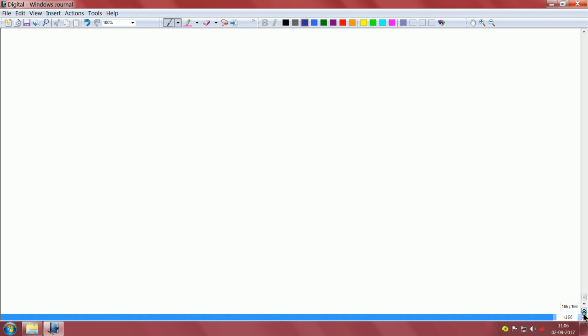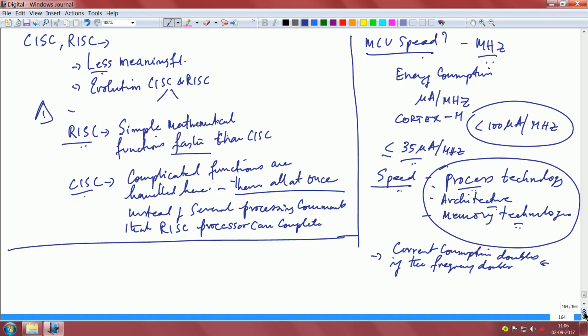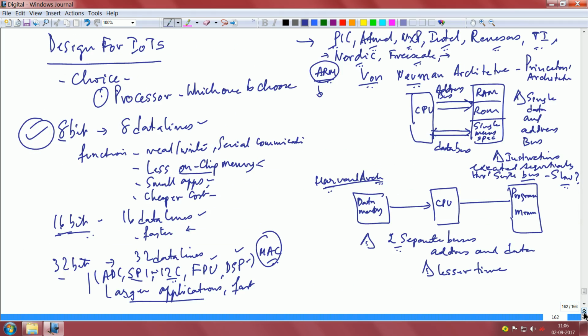Look at the architecture: the basic throughput from a CPU will actually come from these buses. So it is insufficient if the clock here is running at a high speed. It is all about these buses and the architecture of these processors which hold the key.